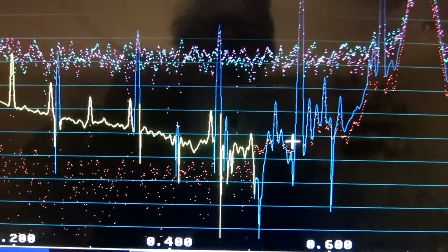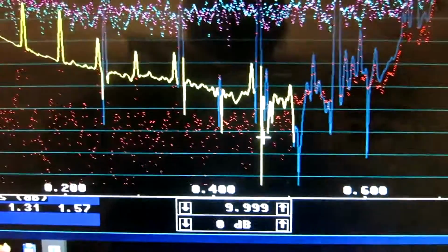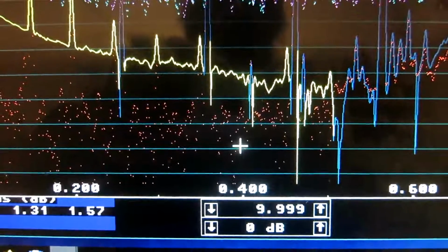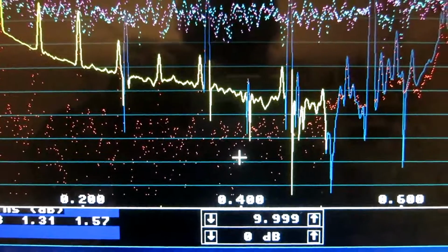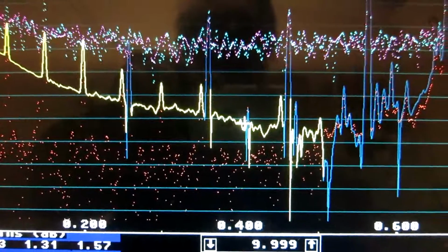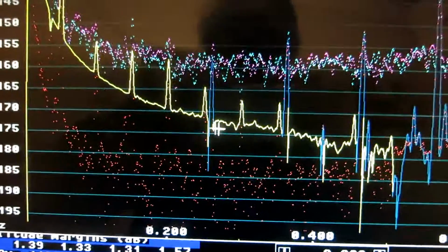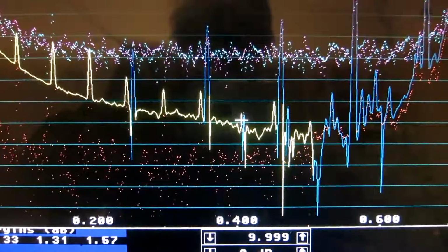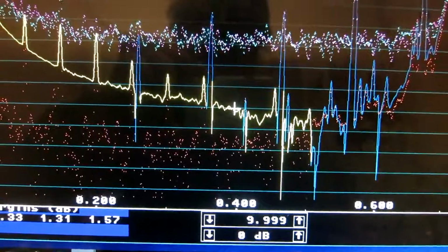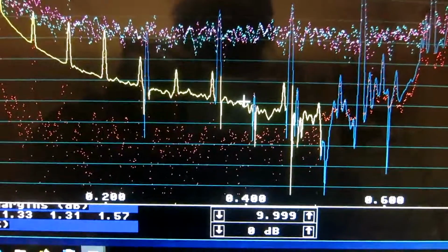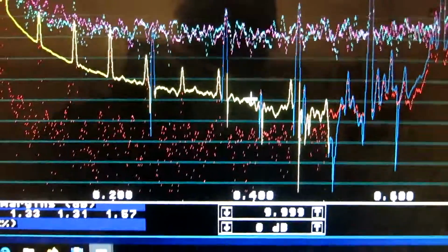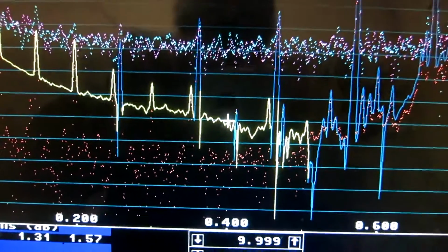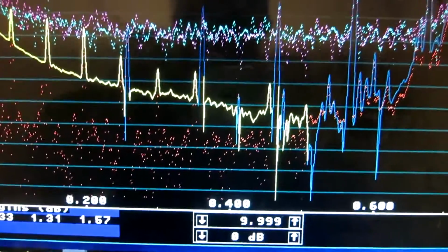So what I do is to extrapolate this curve down like that, and that means that at maybe 400 Hertz the contribution from the center is negligible. But I cannot read from this graph over 400 Hertz. And looking at the shape here, when the curve starts to bend down, maybe this isn't real. So at 400 Hertz, that is absolutely the highest, and perhaps there is an error of 1 dB or so. So I can reach minus 175 for the phase noise at 400 Hz.